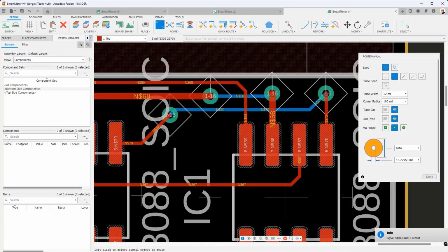This type of scope, in signal and on signal layers, is going to be the key to defining layer-specific rules. This will allow you to define layer-specific clearances, layer-specific widths, and anything that you want to control in that manner. So keep those two key scopes in mind: in signal and on signal layers. See you for the next example.